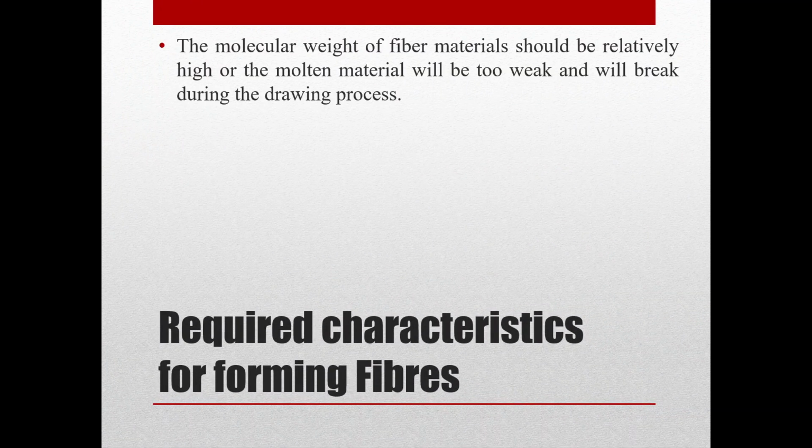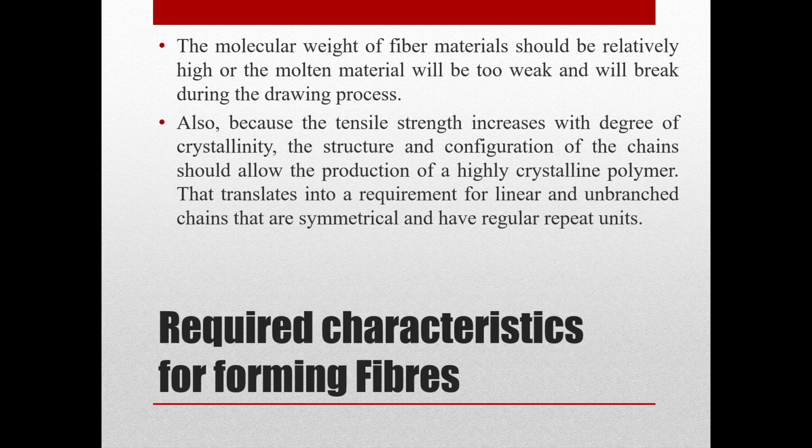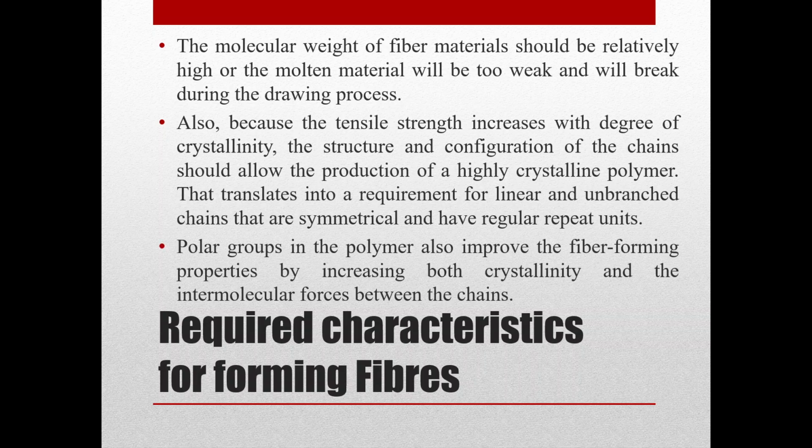So some of the other characteristics required to form a fiber is the molecular weight. The molecular weight of the fiber material should be relatively high, or the molten material will be too weak and will break during the drawing process. Also, because the tensile strength increases with degree of crystallinity, the structure and the configuration of the chains should allow the production of highly crystalline polymer.